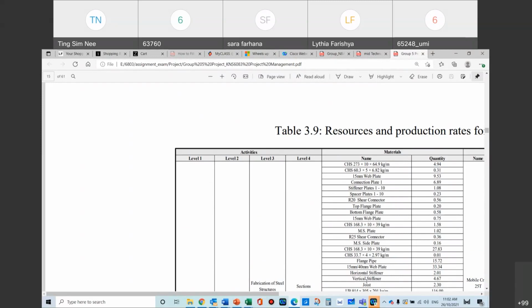It's different if you list down the quantity as just one, and you're just getting the rate from a supplier. When a supplier gives you a rate based on one, it is different from a rate based on 10 tons or 5 tons and all that. The 1 meter cube rate is going to be different from if you're ordering 10,000 meter cube from him, you see. So it does make a lot of difference. You need to get this preparation done. In terms of material, it's more straightforward. It's straight away there. You list down the quantity that is needed. You double check the quantity again.